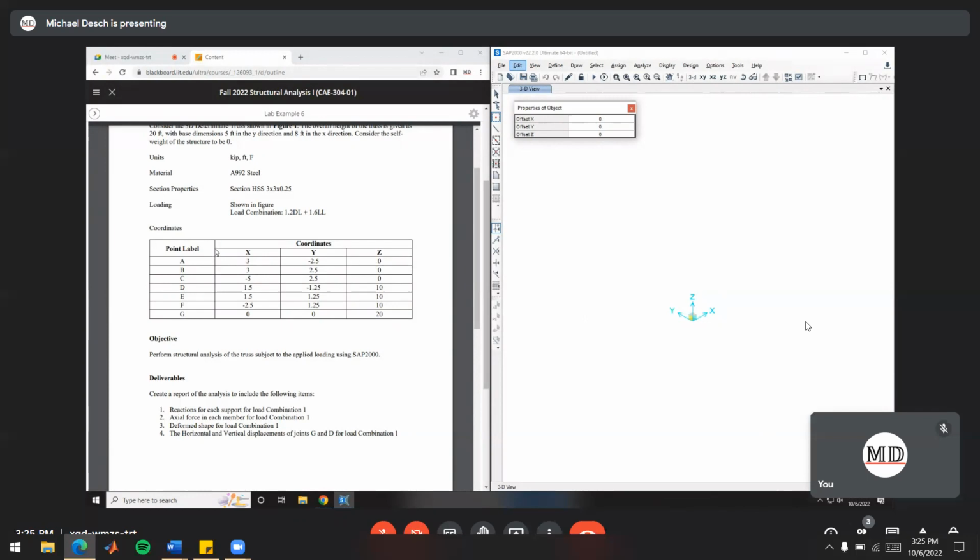So this is a pretty neat trick to put a node at some arbitrary coordinates in your model here. So we're going to put 3 here, minus 2.5 here, and then 0 in Z there. And when we're happy with that, 3, minus 2.5, and 0, we're going to click on our grid point, and it's going to insert the node.